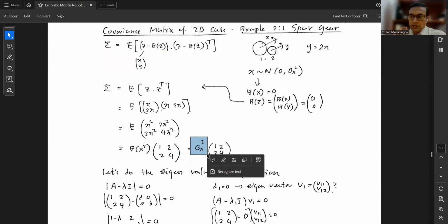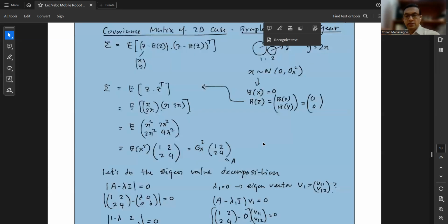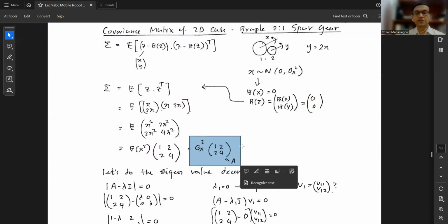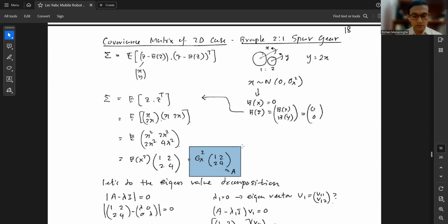You can find out sigma of your device experimentally, and get the square of that, and that is the variance or covariance. And according to this arrangement here, two gear wheels, you get this matrix here. Now this is your covariance matrix of the gear wheel. So this is how you build a covariance matrix of any system. For a mobile robot, you can write the equation and figure it out. For gear wheel, I have just shown you how to do that.